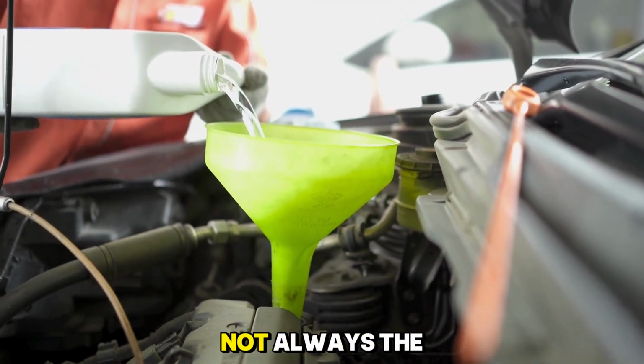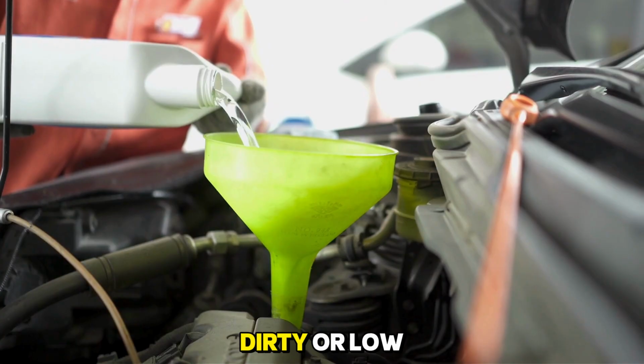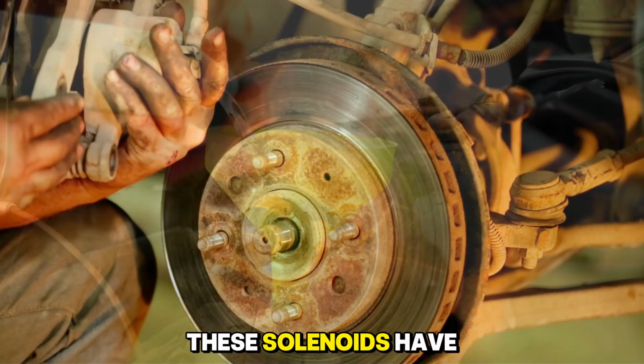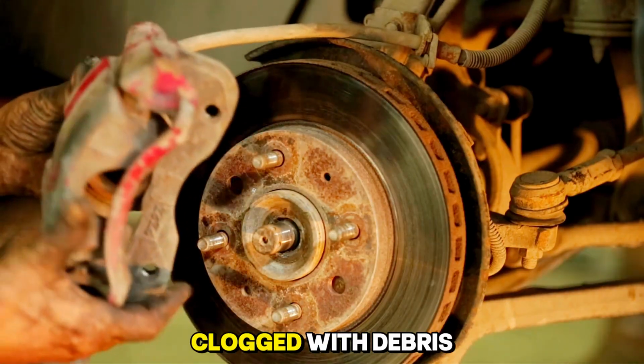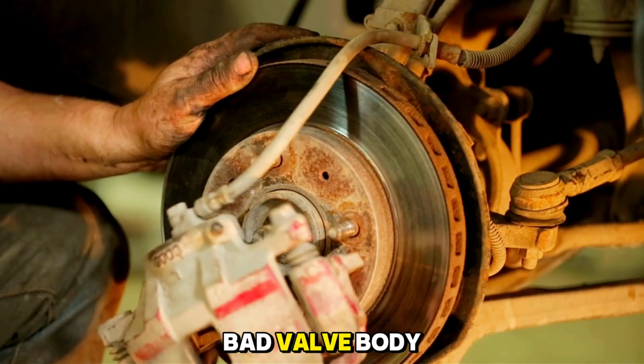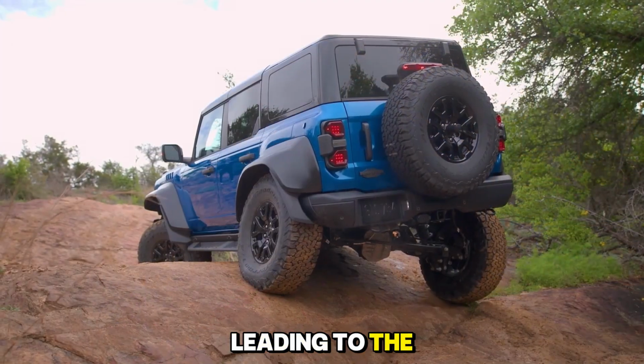The causes are not always the solenoid itself. Dirty or low transmission fluid is a major culprit because these solenoids have tiny screens that can get clogged with debris. It could also be a defective transmission pump, a bad valve body, or damaged wiring leading to the transmission.